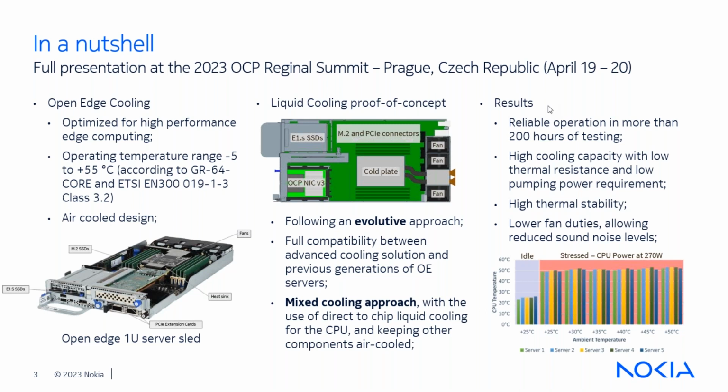Okay. Lucas, I have one question, Magic from DCX here. The question is about the condensation control. So you're introducing another very effective cooling solution, which is direct to chip cooling, which is awesome. But it's relatively easy when we are in the white space, where we can have the proper CDU and lots of automation to get the proper temperature so we don't get into the dew point. So what's your solution on that in the kind of edge application?